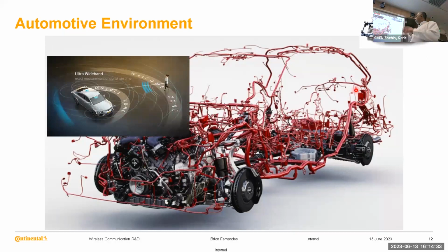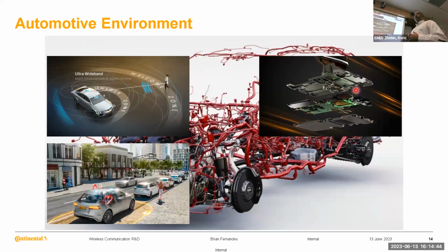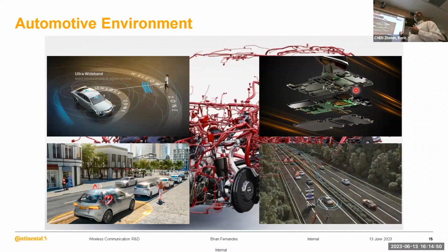So that's what we then build our wireless functions on top of, like communication, sensing, what we call child presence detection. I will explain that later, as well as communication on the highway. A critical aspect that we have to keep in mind, the constraint, is that these vehicles are moving at very high speed, and they could be moving at different speeds on the highway, and they've still got to be able to reliably communicate between each other. So we have to consider phase differences, Doppler shifting, and things like this. So a lot of constraints on the application side itself.